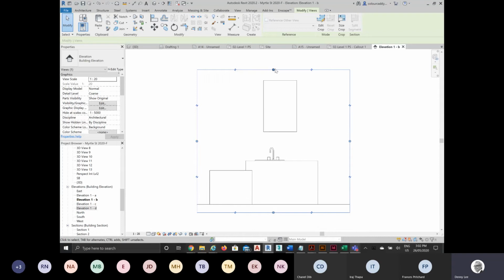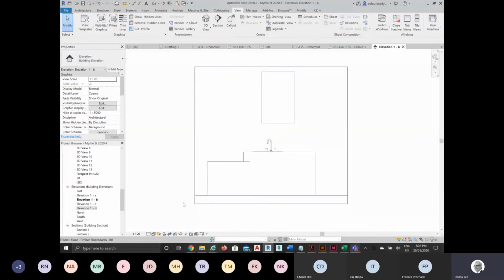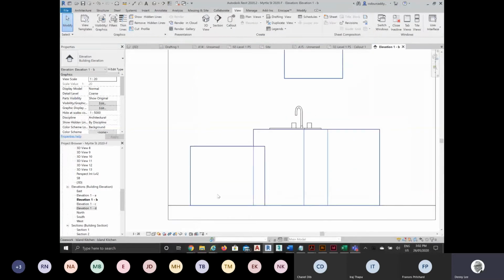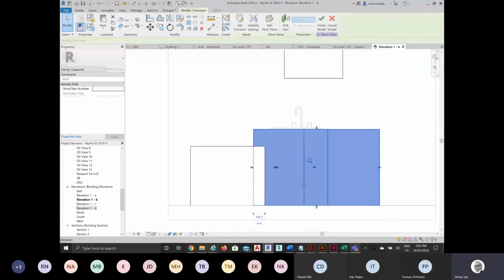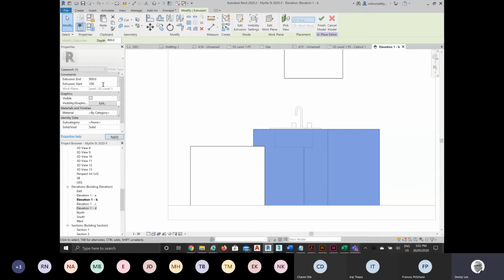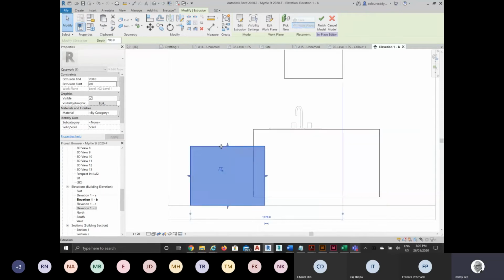Okay, and then we can bring this up and see that overhead cabinet. I might need to include that in the drawing as well, but I'm not sure if this overhead cabinet really makes sense. But if it was to be there, then you would definitely include it in the drawing. Yep, so again, if this is going to be a rotating thing on wheels, then you might do some more modeling. So if we bring the base of this up to, let's say, 100 mil. Right, so I'm making the start 100 for both of these extrusions, so they both start 100 mil from the ground.